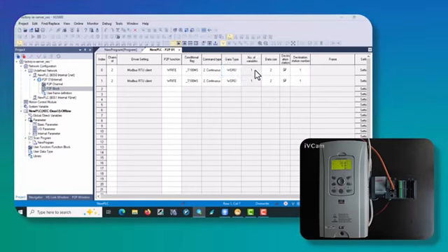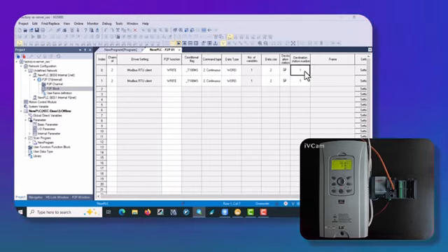Now, for the data size, here I've set it to 2. You can also set it to 1 since you're only going to send a single value to the inverter. My station is set to 1 because my device, the inverter, needs to have the same station number as the PLC. So I chose 1 so that both are set to 1.